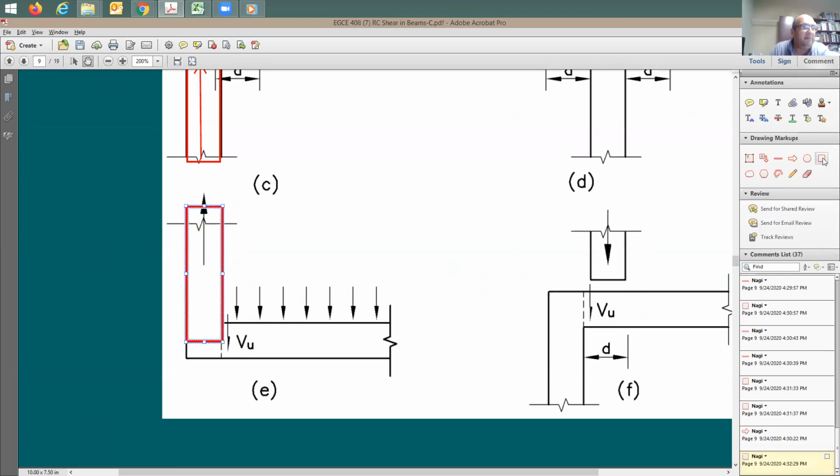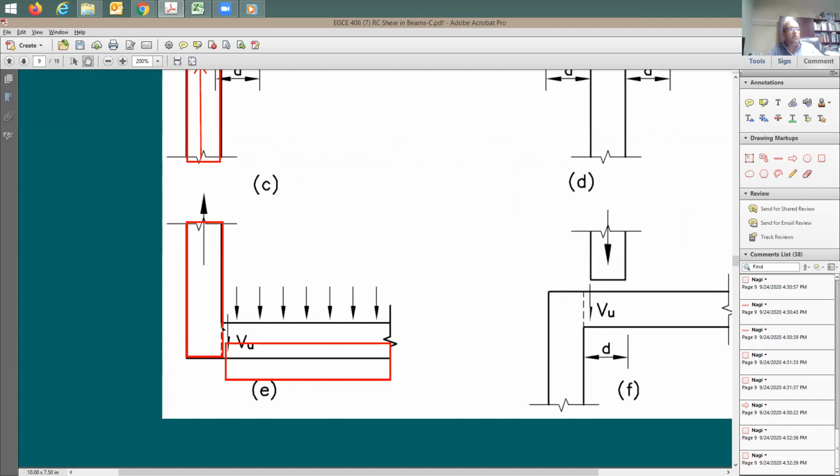And this beam is going to stay in place. Or this beam is going to be coming down, if you like to call it this way. This column here, let's say, is going to stay in place, and this beam is going to be just coming down this way. There is no way that you're going to see here an angle of 45 degrees. Otherwise, this angle is going to work like a ledge. It's going to be an actual support, and failure wouldn't happen.